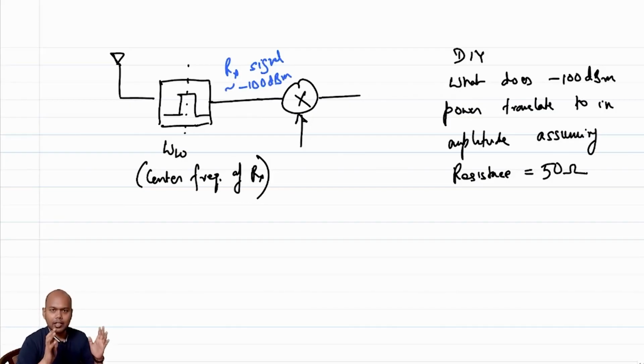If you observe the output, you will see some wiggling on the oscilloscope or the spectrum analyzer. We'll never see perfect zero, because any active device throws out some amount of noise. Now, if the signal that you are processing is weaker than the noise that your amplifier is generating, then you have big problems.